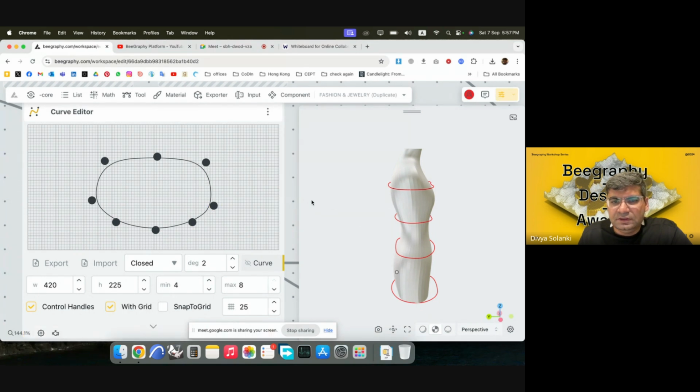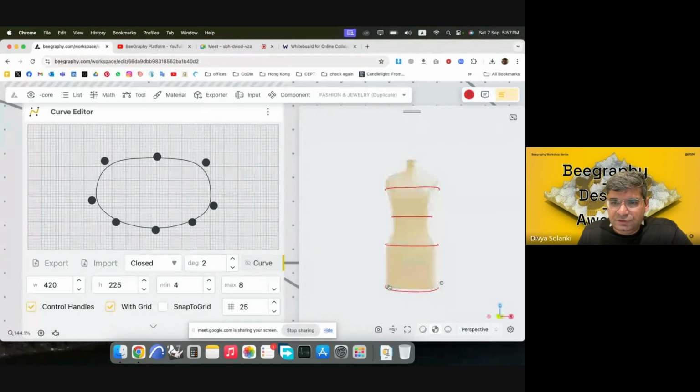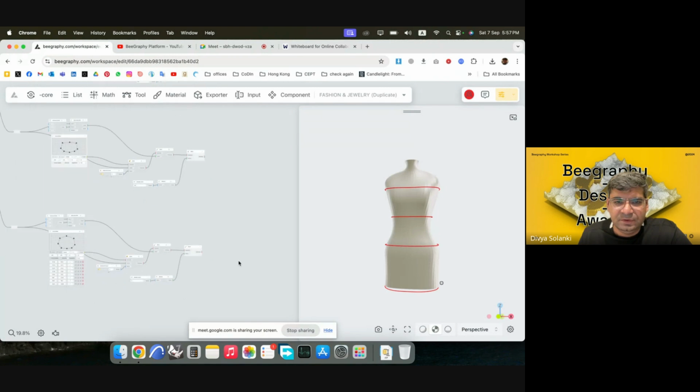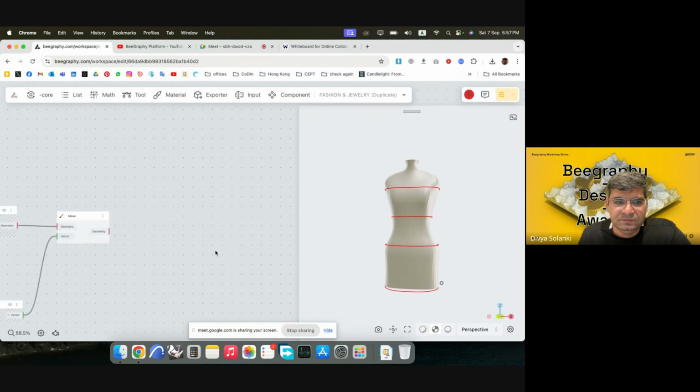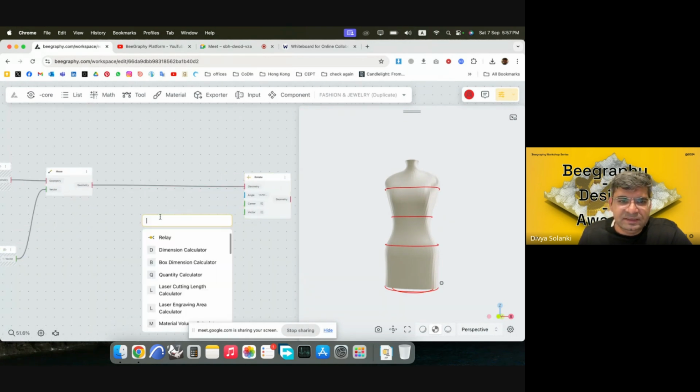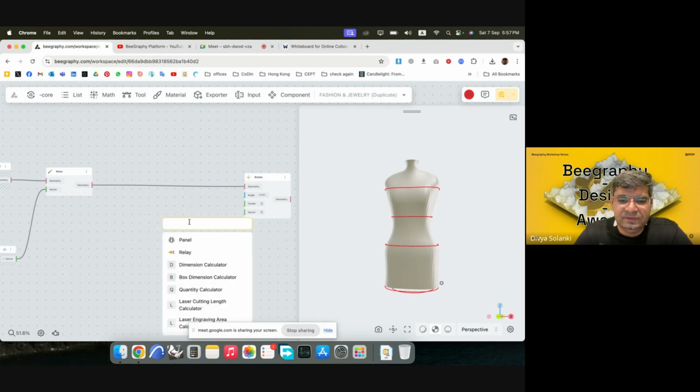Yeah. And then I'll try to rotate the bottommost curve. So for doing that, what we can do is go to the lowermost curve. We will write rotate. We can use the rotate axis tool. You just have to provide it the curve, and then you would have to provide the centroid. So centroid can come from either the grid itself or the geometry.